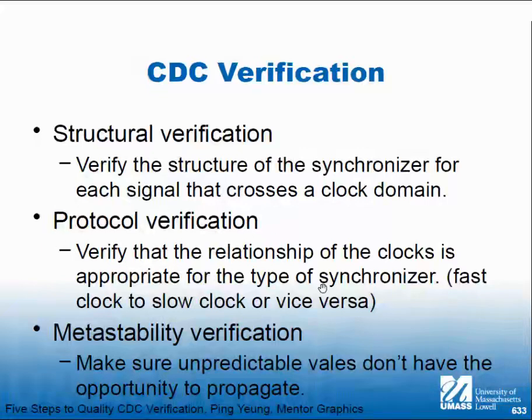Sometimes you have a case where the next state can handle the potential of an unknown state coming through. It is very rare that the protocol will actually handle a metastable state. And it looks like it would in a lot of cases, but the problem is that the metastable state can propagate. So here's an example, the best example: you have an interrupt on a processor.